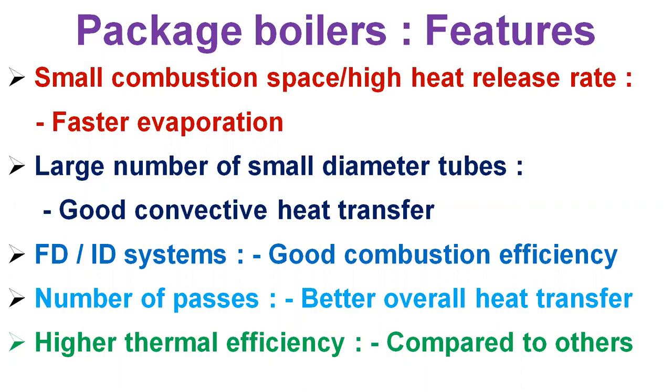So these boilers are classified based on the number of passes, the number of times the hot combustion gases pass through the boiler. The combustion chamber is taken as the first pass, after which there may be 1, 2, or 3 sets of fire tubes. The most common boiler of this class is a 3-pass unit with 2 sets of fire tubes and with exhaust gas exiting through the rear of the boiler.